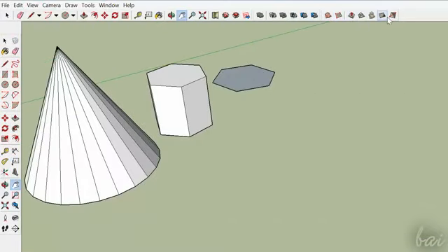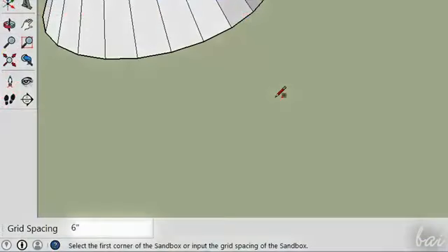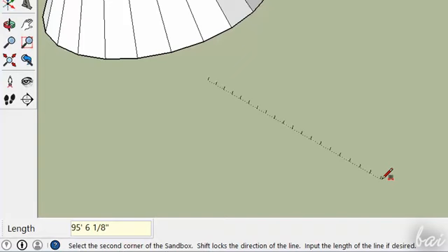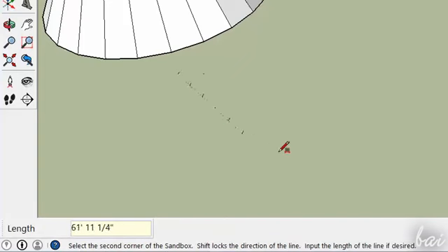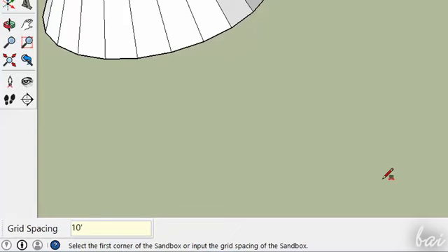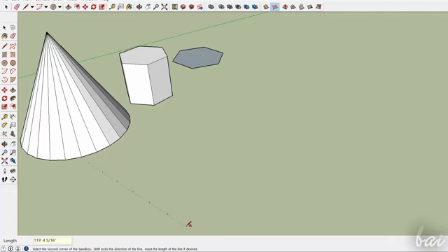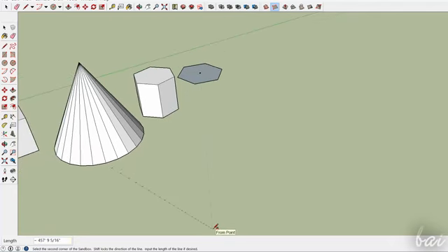To create a mesh base, you can start from scratch. Define the grid size simply typing with your keyboard and using Enter key to apply. The smaller the grid is, the more precise you will be, but be careful, because smaller grids may load your computer too much. Then click on a point and stretch a line. Then fix a third point to set direction and area.